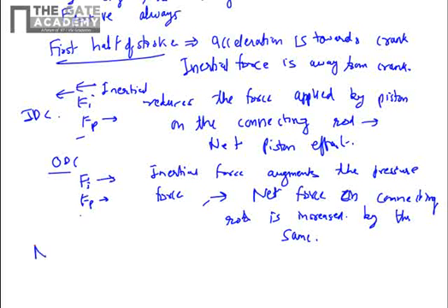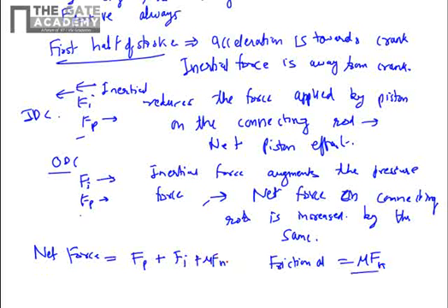So what is the net force on the piston? Net force is equal to Fp, the pressure force, and then you can take the additional thing, that is frictional force. So frictional force is, if you know the normal force between the piston and the liner, that Fn, during the start of the discussion we said, then coefficient of friction multiplied by Fn will be the friction force. So plus mu Fn, the normal force between piston and liner.